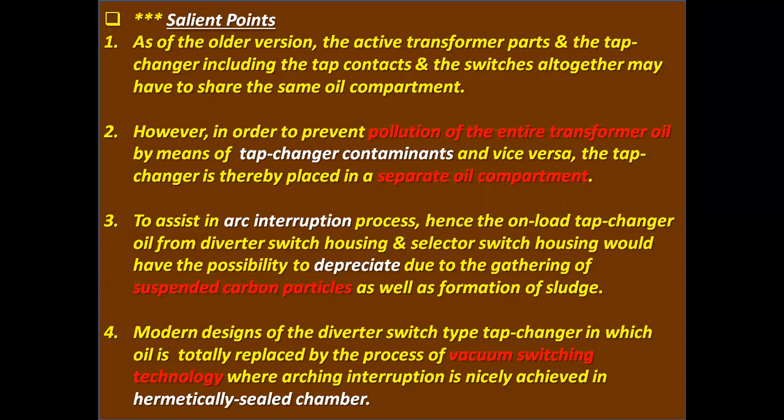That is, everything is in the same oil compartment. However, in order to prevent pollution of the entire transformer oil by tap changer contaminants and vice versa, the tap changer is placed in a separate oil compartment.